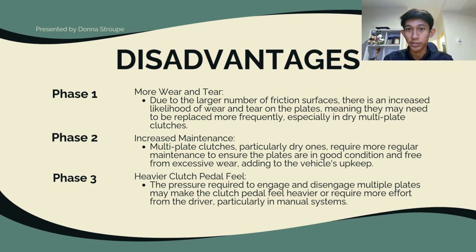When it comes to advantages, there must be a few disadvantages as well. So we have three disadvantages. The first is more wear and tear due to the large number of friction areas. There is an increased likelihood of wear and tear on the plates, meaning that they need to be replaced more frequently, especially in dry multi-plate clutches.